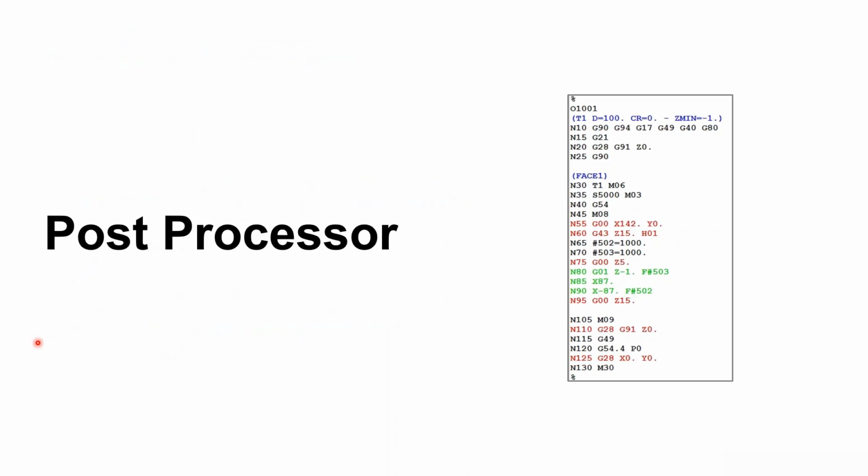Post-processor, yeah, that is a very important link between the CAM software and the CNC controller. And with the HSM product, we have an open post-processor, and that means that it's possible for anyone to customize the post-processor. But if you buy a post-processor from us, or if you download a free post-processor from the Autodesk library, it is possible to adjust it by yourself, or we can help you to adjust it.